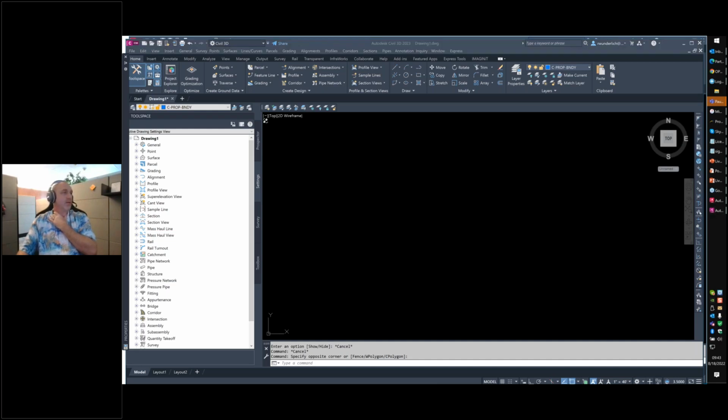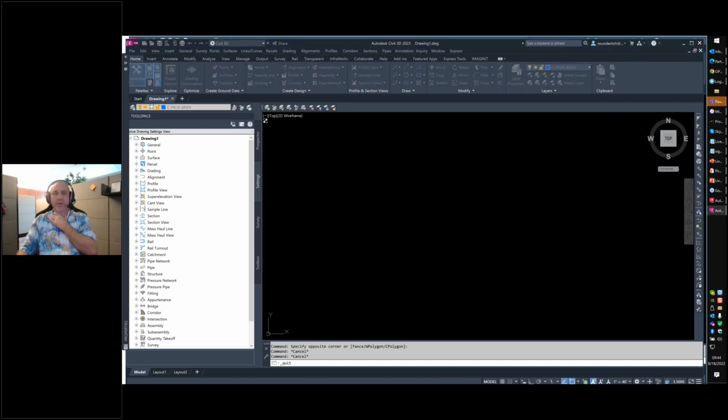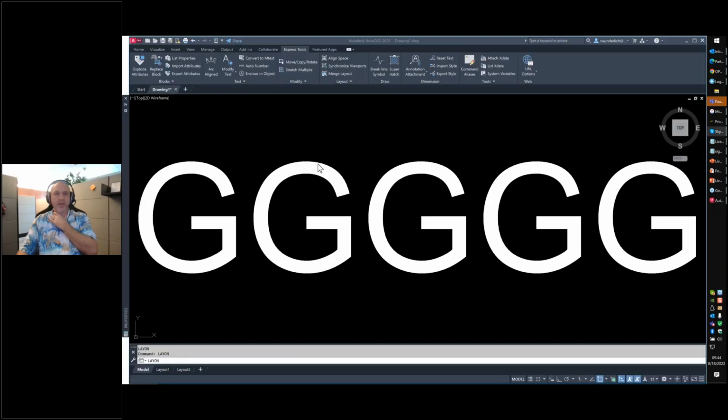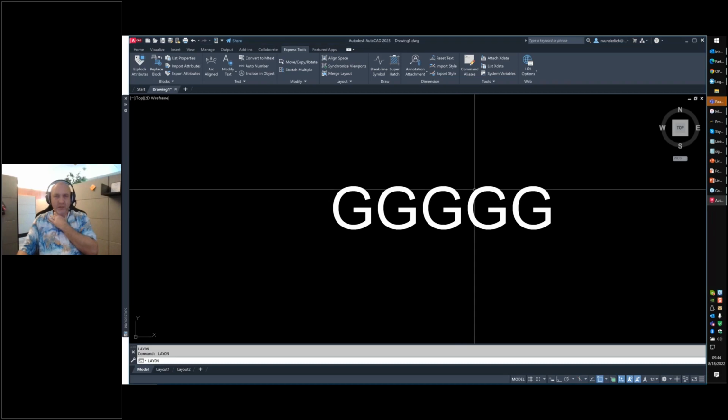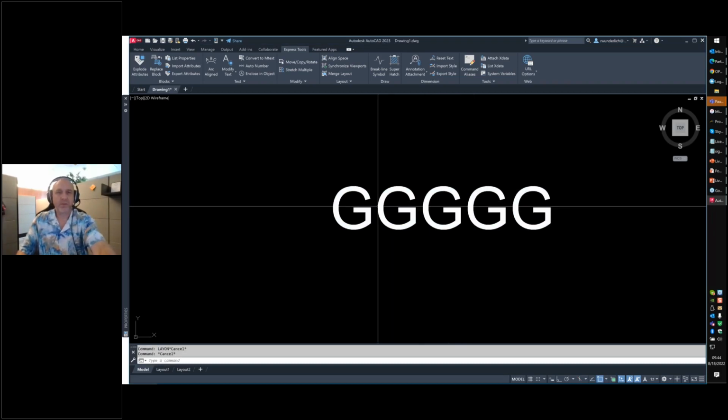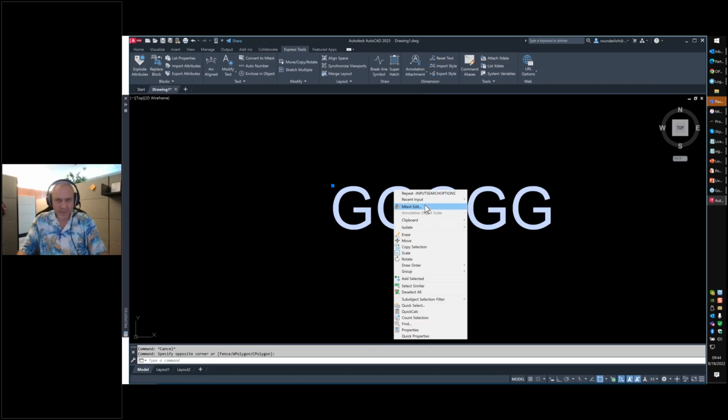Now let's see. Let's see, highlight text and right click to change text. You're talking, we come in here, let me move this down here. So we're talking, click on this, right mouse click, mText edit, draw order group. These are all of your regular pieces in here for what's available that way with a right mouse click. You'll see that I don't have the ability here to change the text to all caps. We could modify the CUI menu so that this pop-up does have change text, or tcase, sorry, the command is tcase.